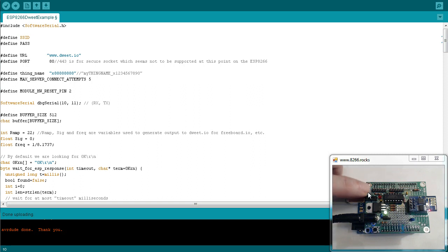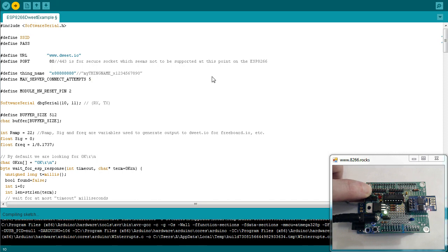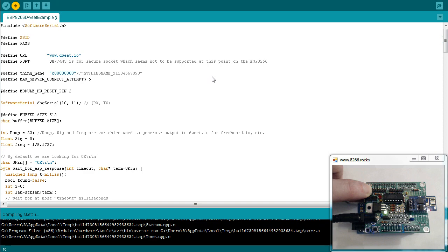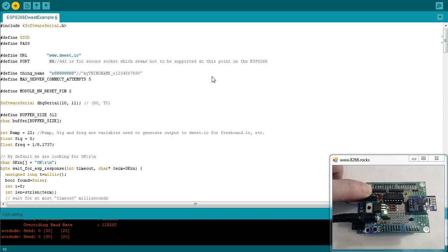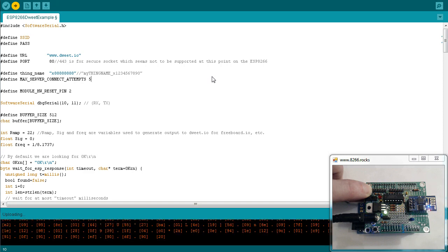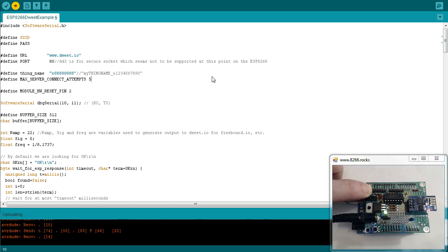We need to hold this down before we click on the upload button, and keep it down until the sketch has finished uploading. So the upload is done, and I can release it, and our sketch is now running.